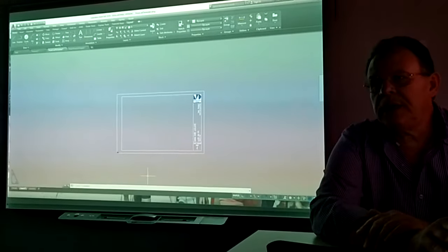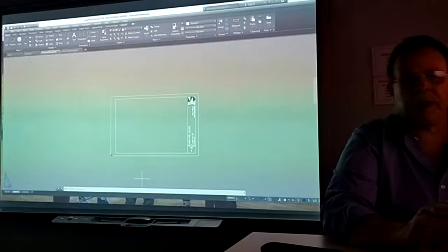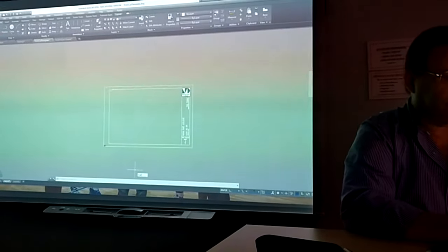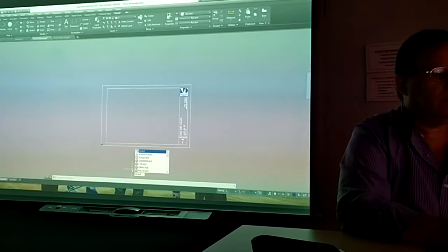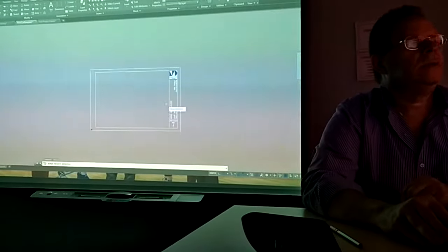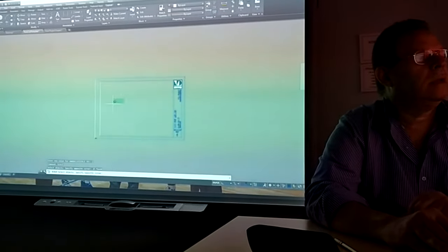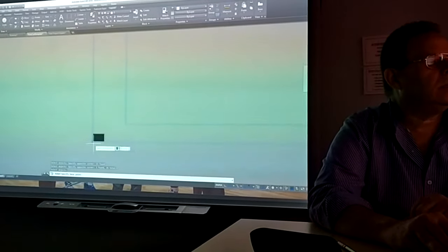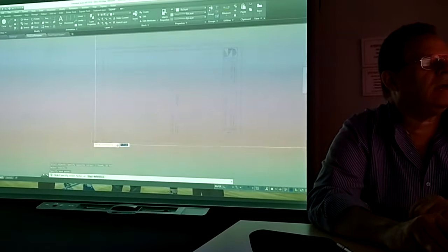Then type in scale. That's a command, scale. You want to shrink it down, right? Scale. See? Takes a while to think. Enter. So I'm going to highlight it, right click, enter, specify the base point. This is my base point. And once I have the base point,